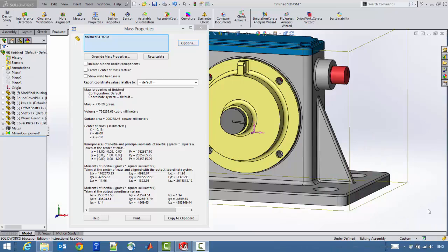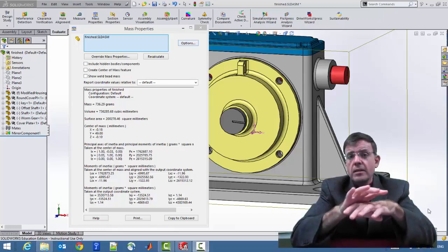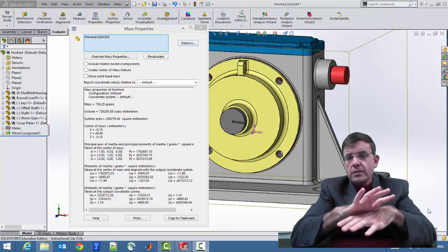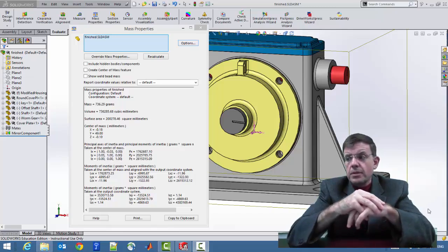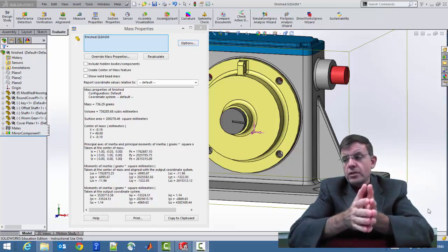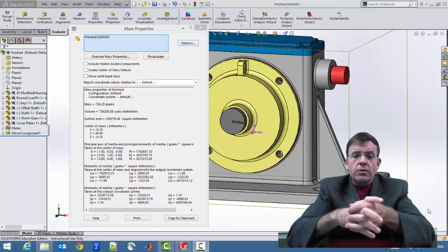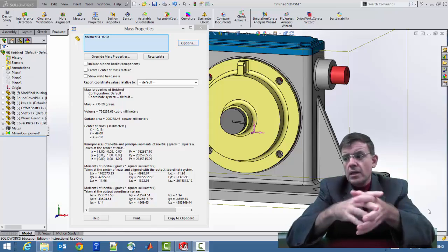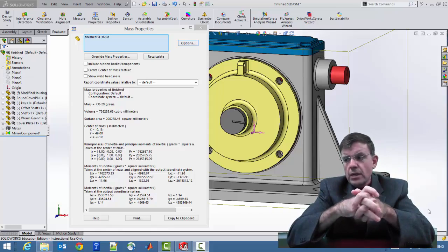Now we'll round up this exploration of mass properties with one last important subject, which is the ability to establish and select the particular coordinate system about which you want to report certain numbers. Now, you can imagine, of course, the mass is fully and wholly independent of the chosen coordinate system. Same thing with the location of the center of mass, surface area. All this stands to reason.